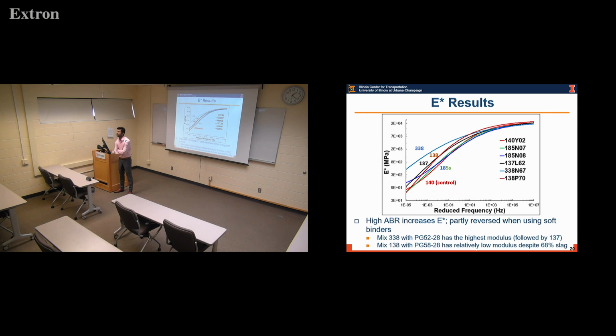Yeah, just a follow-up comment to Isaac's question. If you're not sure whether this area is homogeneous for core drilling, GPR can definitely help, right? If you're not sure it's the same area in 10 years, you can run this continuous test several times a year, or at whatever frequency you want, and make sure that this particular patch is the same right after construction, and you can keep taking cores from this particular patch over the years.